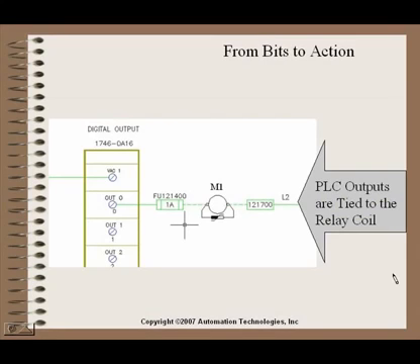They can be manipulated inside the PLC program. Likewise, on the other side, we have our PLC outputs, which is a different type of card that interfaces directly to our relay, motor contactor M1. You see it has a surge suppression device around it to protect the PLC output. Also a fuse that protects the output. But generally, the main thing you have here is this output directly from the PLC that goes to a relay coil to be able to operate some kind of real world device.